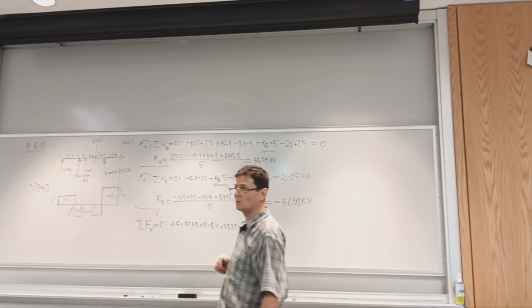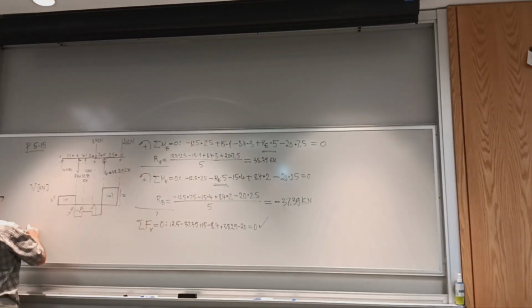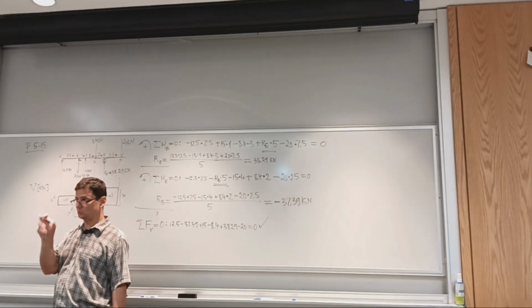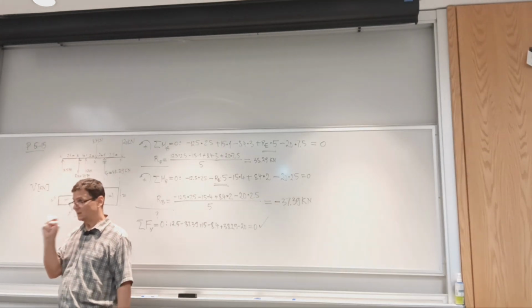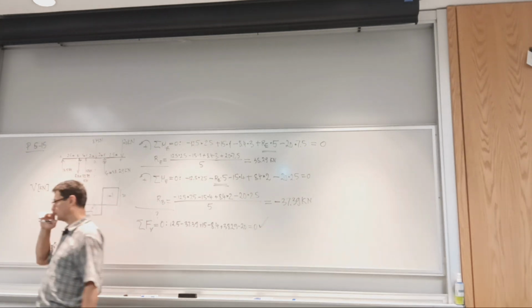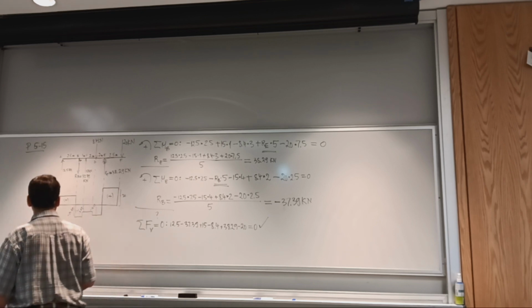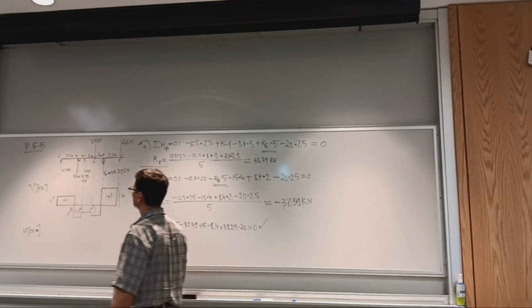All right, can we move to the moment diagram? Moments will be in kilonewton meters. Again, it's not stress analysis time. Once that time comes, you need to change to newton millimeters, to use millimeters, or millimeters to the power 4 for area moments of inertia, to get your stresses in megapascals. So moment will be in kilonewton meters.